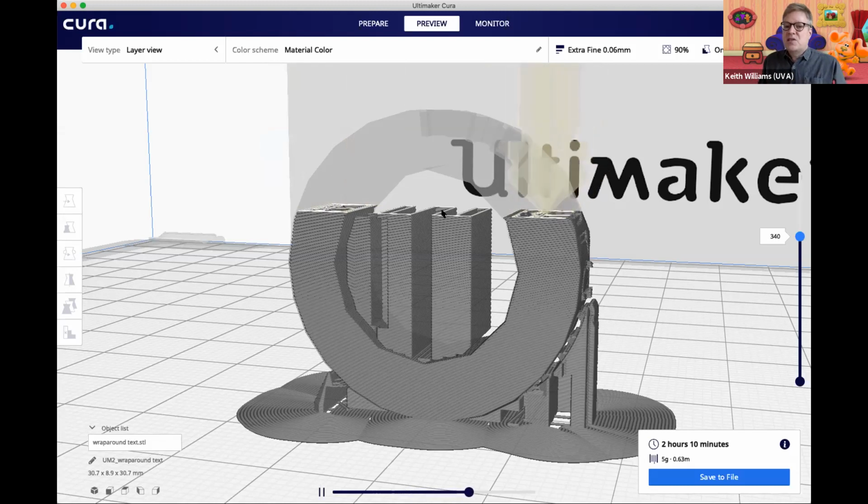Okay, so some vocab you've got. You've already got slow axes and fast axes. The slow axis is the vertical axis, right? And also take a look at this: what limits the resolution along the vertical axis, along this direction upwards? The layer height, right? How many layers you slice it into. In this case, I sliced the holy whatever out of this thing, and I've got 500 layers, so this is about as slow a print as you're gonna get.